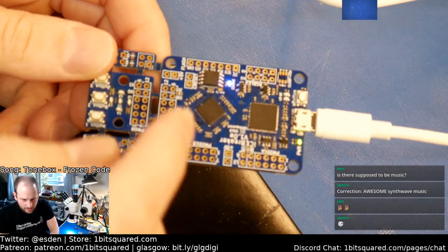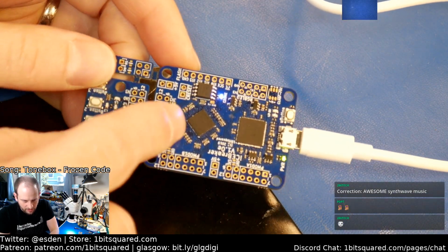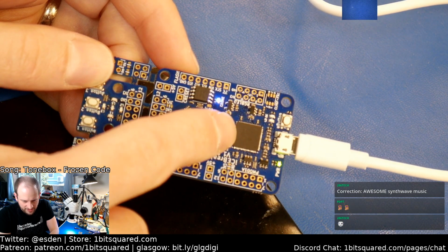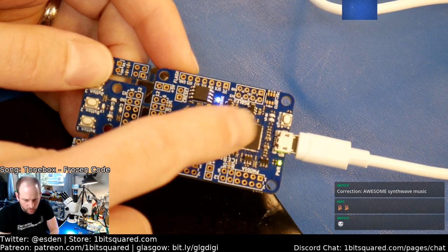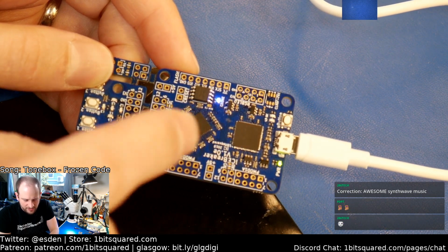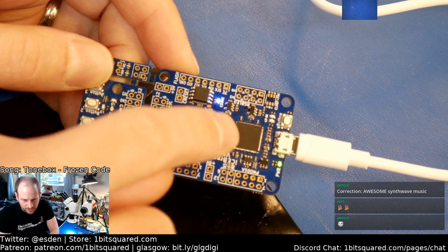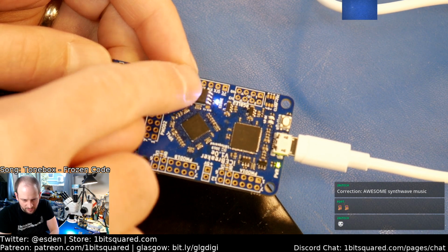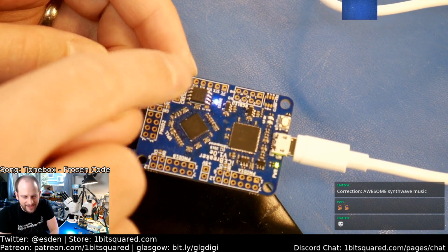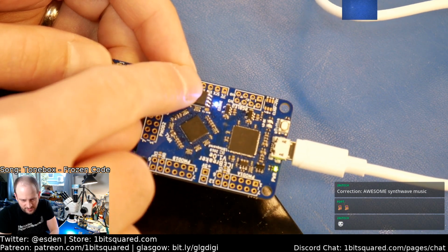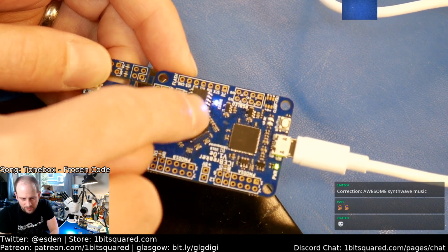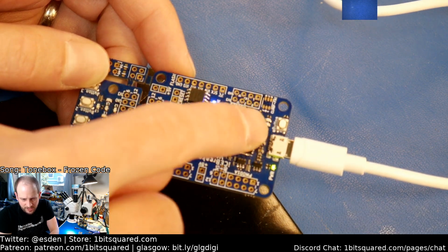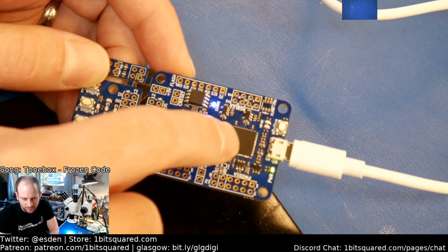iCEBreaker currently is put together out of the iCE40 UP5K FPGA, and it has flash, and it also has an FTDI, USB to serial or SPI. So we use the MPSSE engine in the FTDI chip, and we can flash the flash chip and put the bitstream in there, or the executable for the core that we have in the FPGA, as well as use it as a serial interface. So all the USB magic is contained in the FTDI chip.